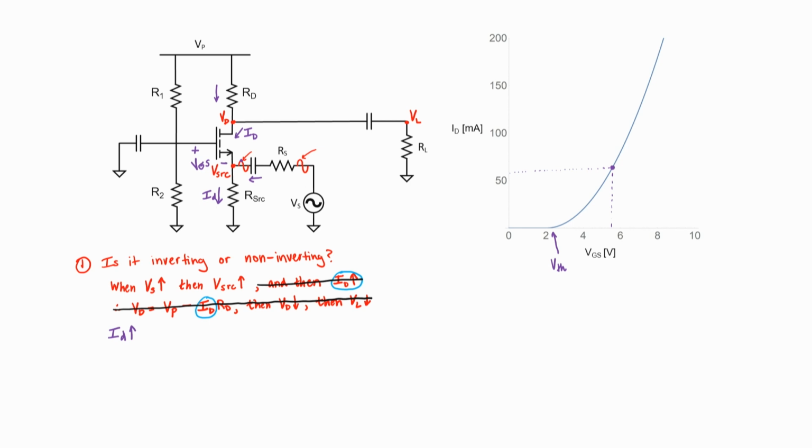Let's now consider what happens when we apply our signal. When our signal increases, our gate source voltage actually decreases. On the other hand, we move up this curve when our signal voltage decreases. Since these up and down movements of the gate source voltage show up as changes in the drain current, the transistor can function as an amplifier. In fact, this ratio of the change in drain current to the change in the gate source voltage is called the transconductance. So this really represents the amplification action of the transistor.